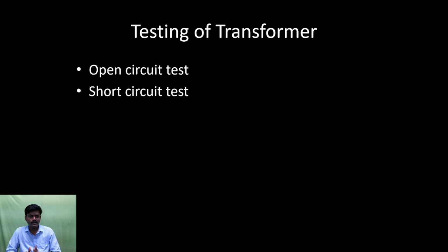Normally primary turns is 30, secondary turns is 50, which means it is a step up transformer. Normally primary turns 30, secondary side 15, means it is a step down transformer. If the number of turns is reduced, it is a step down transformer. If the number of turns increases, it is a step up transformer.